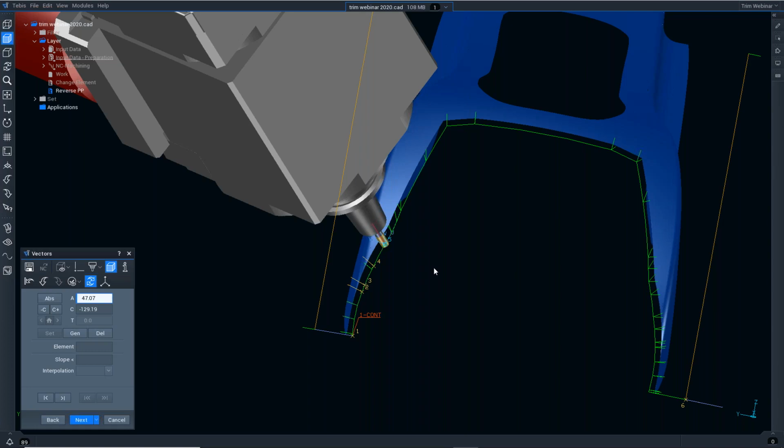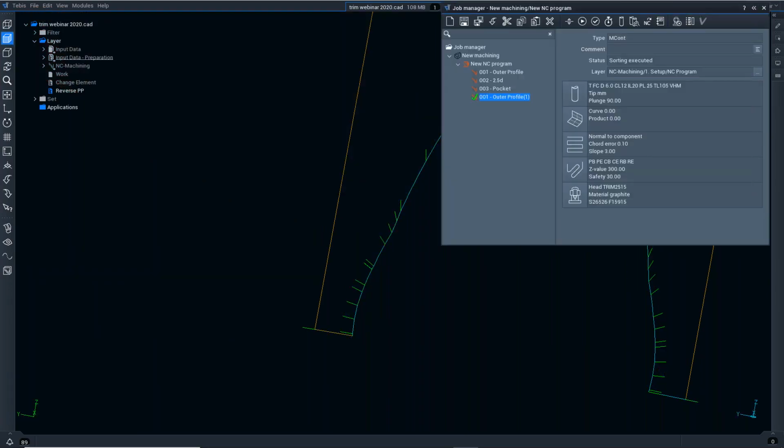What that means is, because teach-and-learn programs are very difficult to modify, we have all these angular movements and a lot of difficult numbers to deal with. By doing this, we can then make adjustments to the toolpath contour. We can make adjustments to the finished final part. And it's a lot simpler and cleaner to work in Tebis this way rather than having to hand juggle code inside the machine. Also an awful lot safer. So that in a nutshell is the basics of the Tebis process.